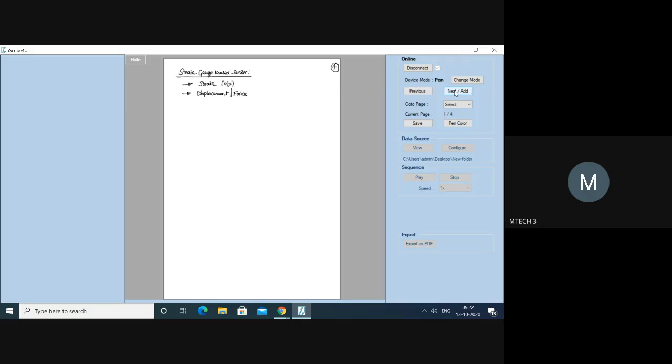Okay, correct. Now, can you measure the strain as a mechanical parameter? If the strain is smaller, try to understand carefully. I have applied a load, just observe. So this is my load cell. I have applied some load, let's say 1 kg. Now some deflection is going to occur, definitely some small one. I'm exaggerating. Now you are going to measure this, which is nothing but your change in deflection.